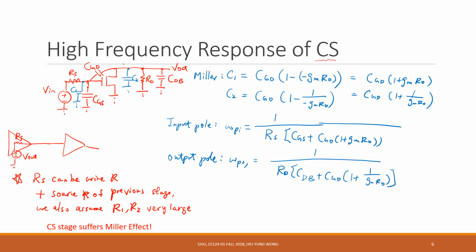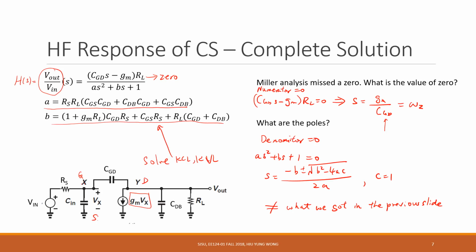So that is the source of the approximation, right? In the derivation, as long as our A is correct, then this is correct. However, we always use the DC gain as the gain A. That's why this is an approximation. Okay, so what you need to take home is that it missed the zero, and also the pole is just an approximation. Okay, so that's what you need to learn so far.